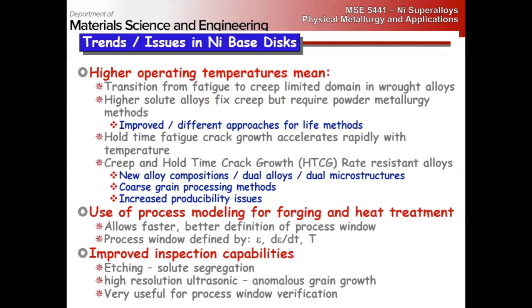The discs have to be polycrystal, random textured. There's no good active cooling mechanism for them. They're just this big rotating hunk of metal. So going to higher temperatures means the design criteria is shifting away from fatigue towards creep.